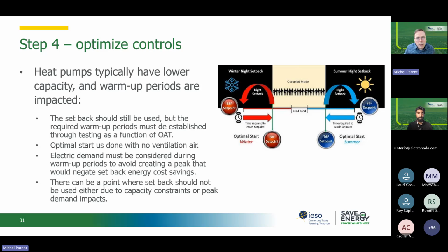Your supplemental heating, if it's programmed properly, will come on, because if the BAS sees that the heat pump cannot meet the load, it will actually call on the supplemental heating to come on. So now you're meeting your pickup heat using the inefficient source, which would be your boiler, instead of using your heat pump.